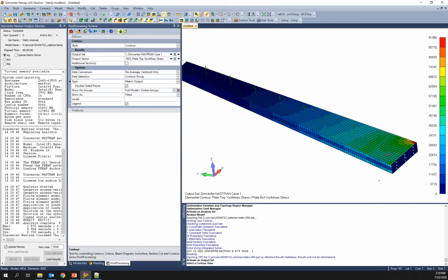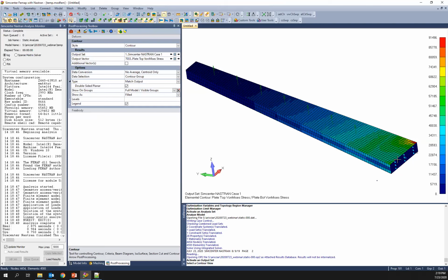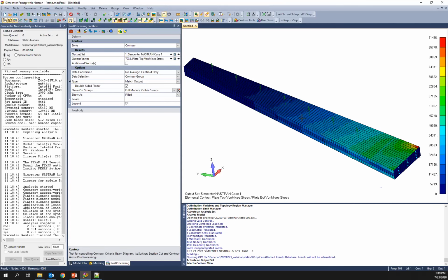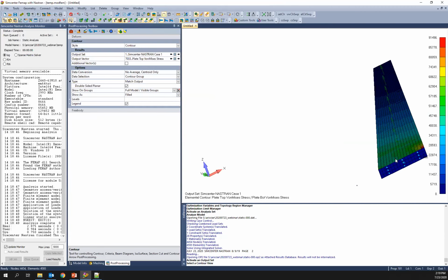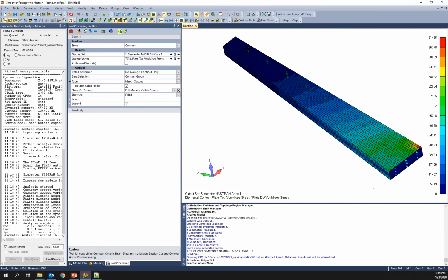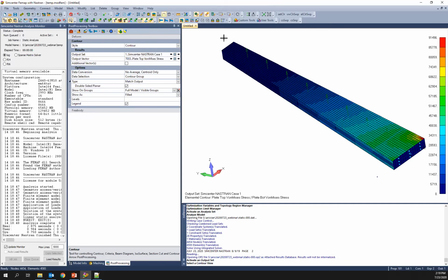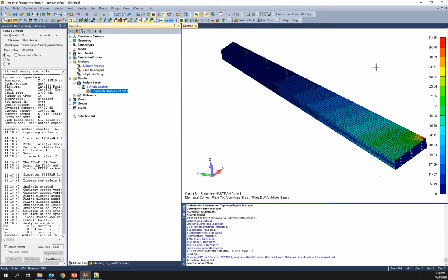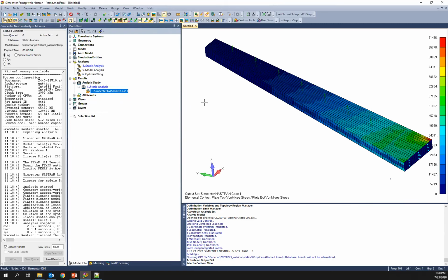If you remember my initial design, I have uniform thickness here, and so it's not thick enough here in terms of the skin thickness at least, and it's overkill near the tip. So what I want here is for my optimizer to taper this wing a little bit so that I have material where I need it. And right now you see we have issues here, and we have potential to decrease the weight of this wing, at least from a stress standpoint, based on this result.